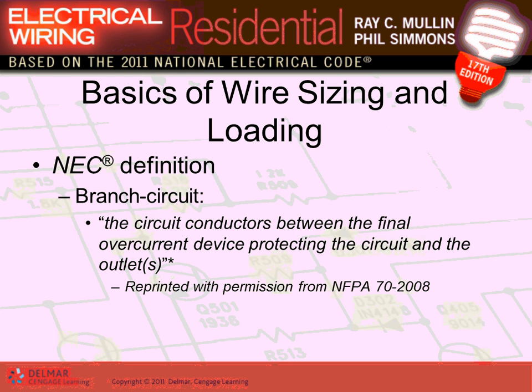There's a few things. So before we start, now I gave you guys the full picture. The full picture is we're laying out receptacles and lights and equipment, and we're circuiting them. Now the circuit that I have just showed you is called the branch circuit. They define the branch circuit as the conductors between the last overcurrent protective device and the outlets, which is that one. So we take it from here, all the way, and feed all of these or some of these lights or receptacles. That's called the branch circuit. Any comments, guys, about the branch circuit? Derek, my friend, when it comes to the electrical code, there are 3 circuits you must understand fully.